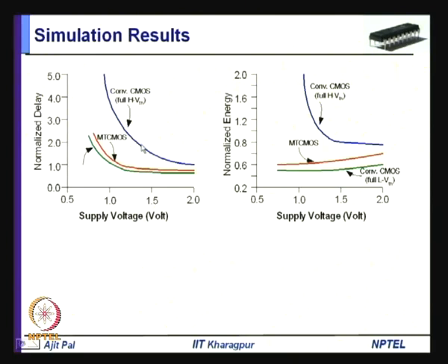But leakage current reduction will be significant. In other words, we can tell that leakage current will correspond to high VT transistors, and performance will be very close to low VT transistors. So, you are getting leakage current corresponding to high VT transistors, performance close to the low VT transistors.